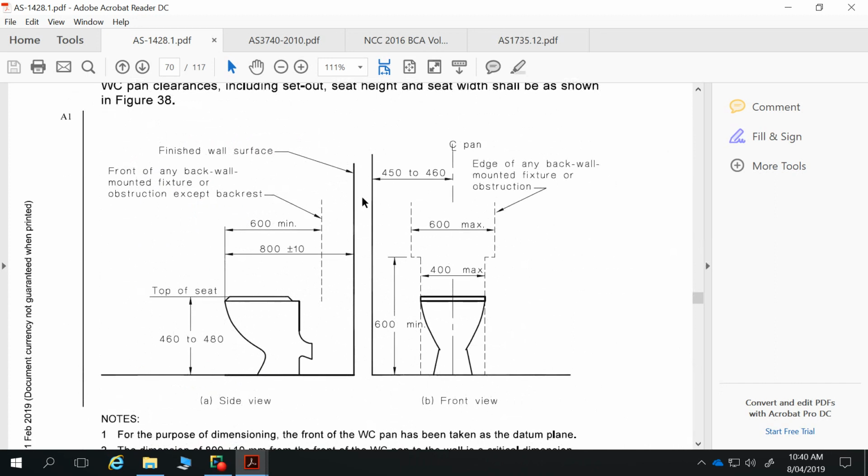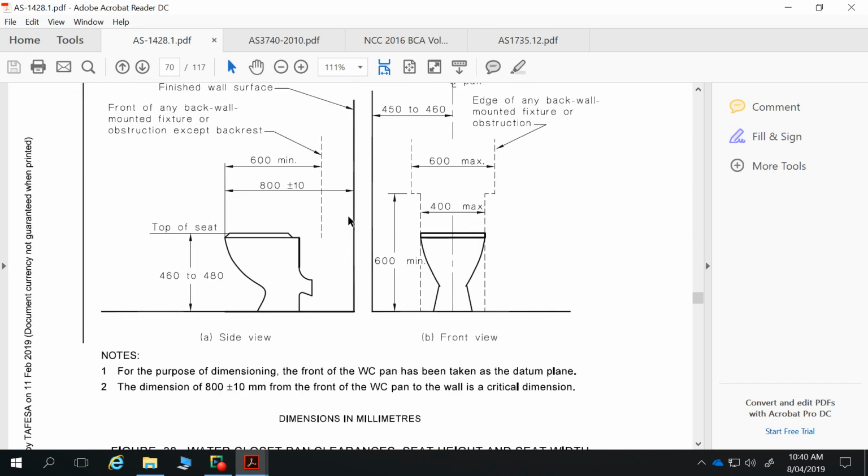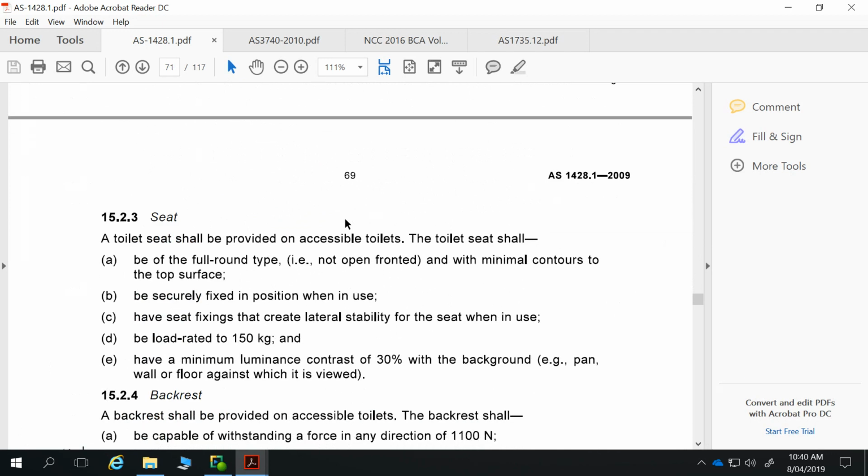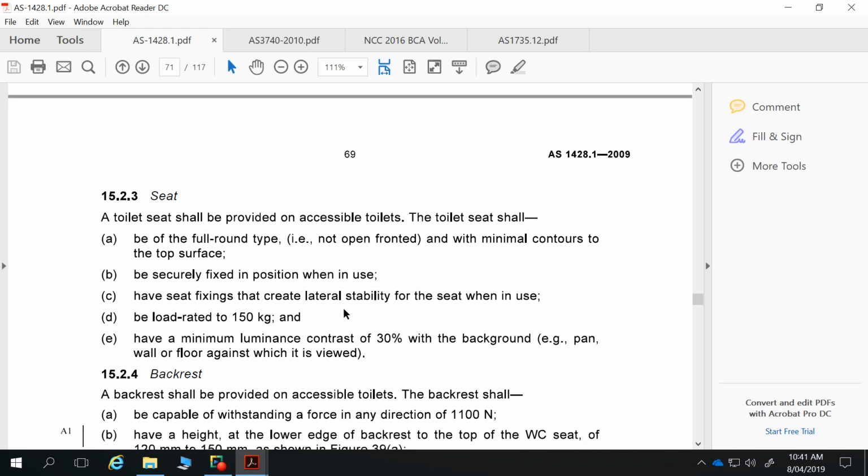But the important thing for us in this project are bathroom facilities that are disabled compliant. Now you're fairly lucky in this manner, in that you have those bathrooms which are already set out on Revit to enable those circulation spaces, and the simple approach is to stick with those bathrooms and those circulation spaces as set out, because you know that they're going to be compliant.